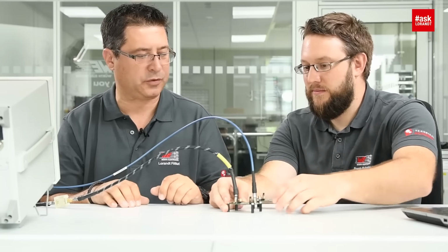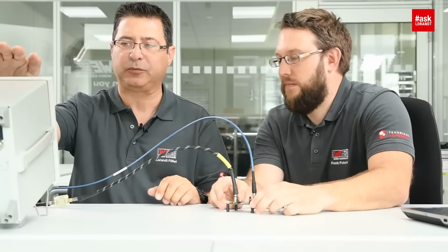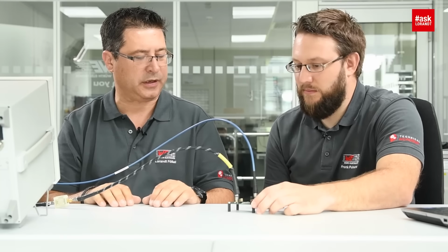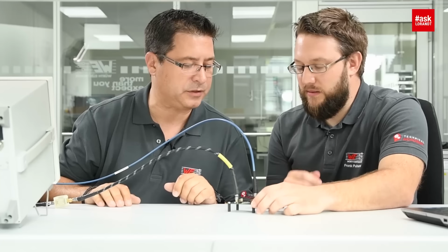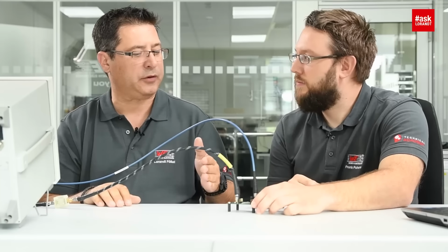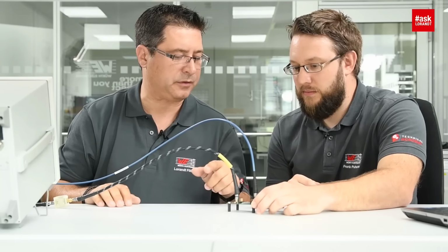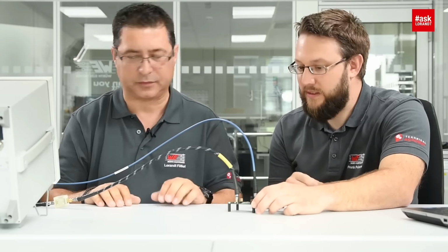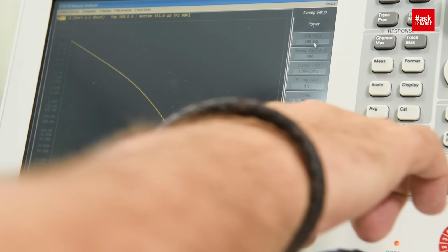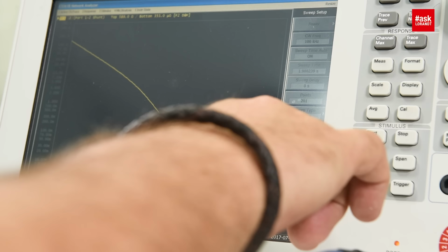Great. So first of all, we will measure with the network analyzer with an internal DC bias source. The first one is the NP0, 10 nanofarad. You have ferrite beads, and the ferrite beads are always the same value? Yes, that's always the same, to have everything the same. DC bias on.